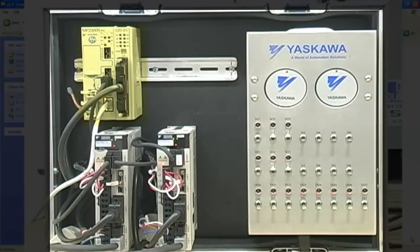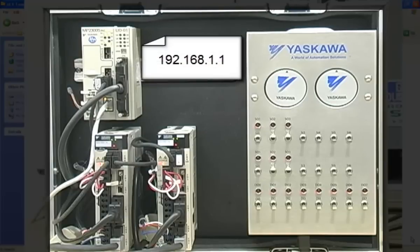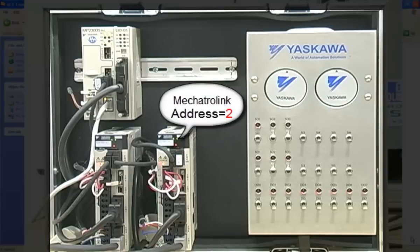So this kit should be set up with the MP2300Siec controller. The config switch should be on in the upper bank of DIP switches, and the E-init switch should be on in the lower bank to set the IEC controller to the default address of 192.168.1.1. Also, the configuration assumes that the left Sigma 5 amplifier is set to address 1 and the right Sigma 5 amplifier is set to address 2.